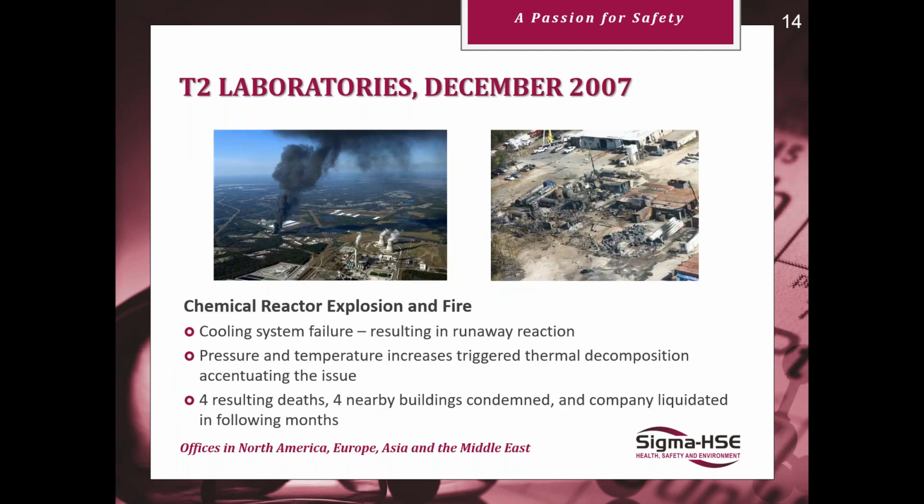So coming a little bit more recently, there was an incident at T2 Laboratories in 2007. This is in Florida in the US, a chemical reactor explosion and fire. There was a cooling system failure on a reactor, and there was no backup basically for the cooling system. And again, there was a runaway reaction. Pressure and temperature increases triggered thermal decomposition, which again meant the pressure and heat, the rate that they were being produced, increased further. Small number of deaths nearby and capital damage.